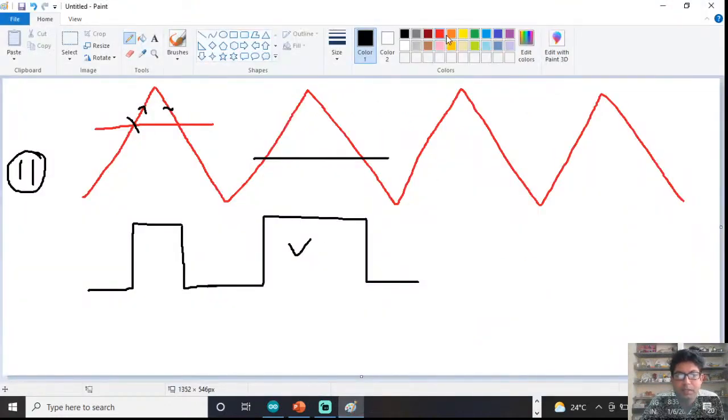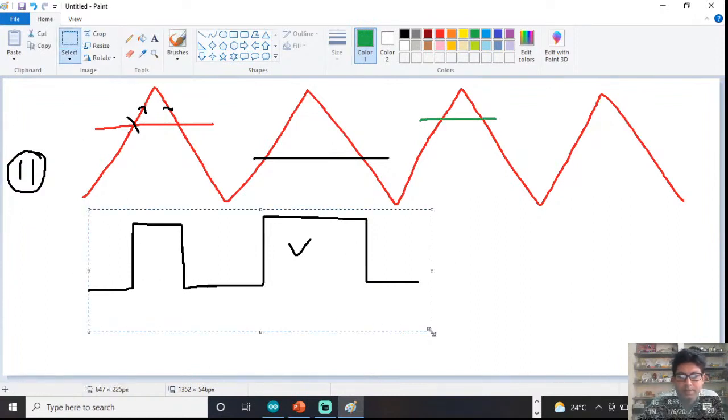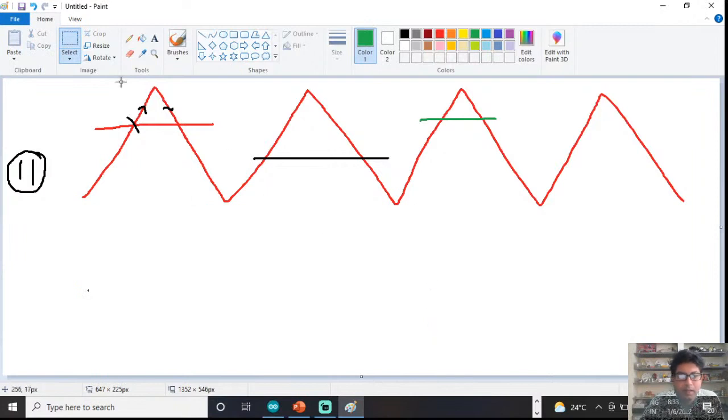That means if I take another thing here, if the pulse is high, once the compare match occurred, it will clear and hold it, and while down counting, when it matches again, it is going to high. So you see, we are just getting the inverted pulse.